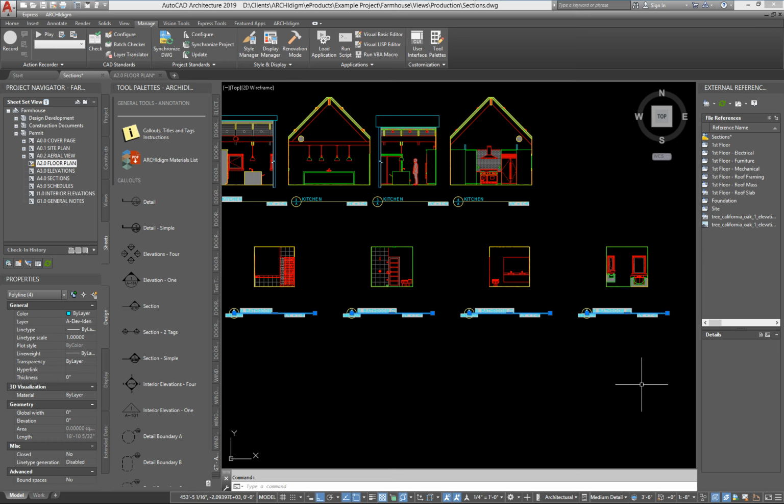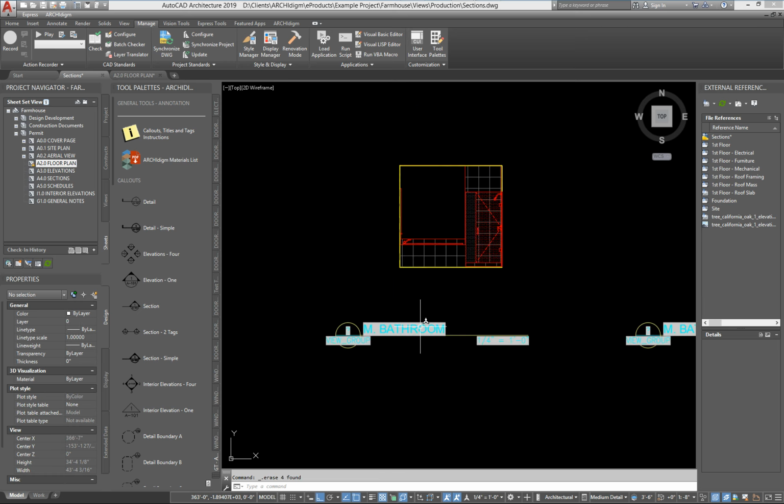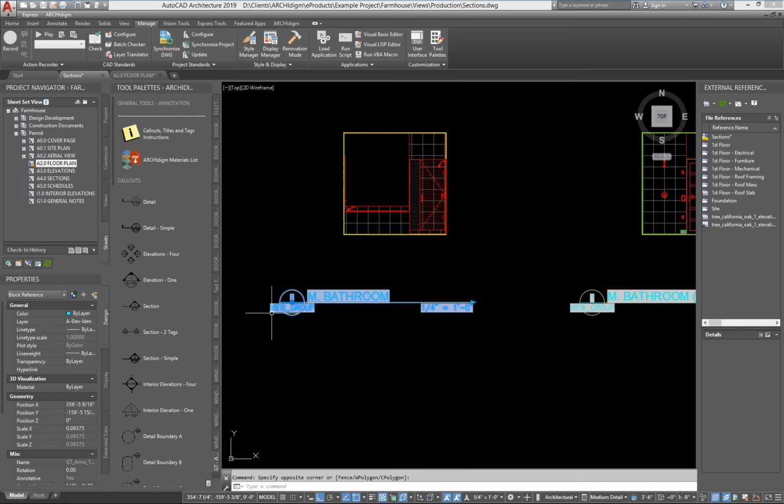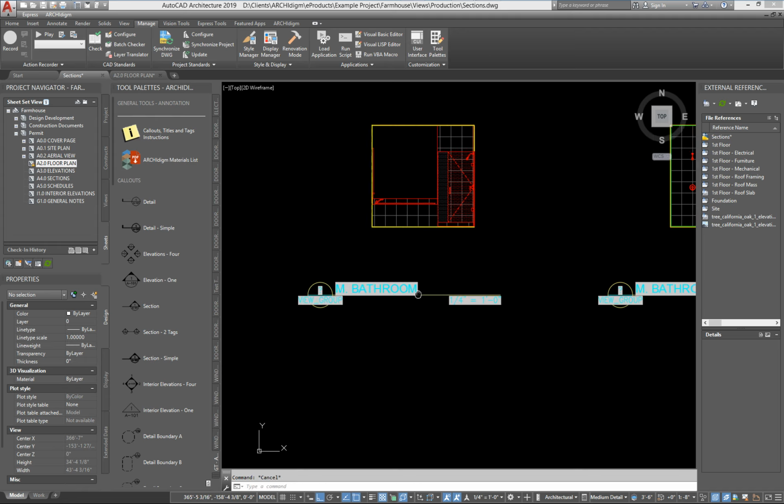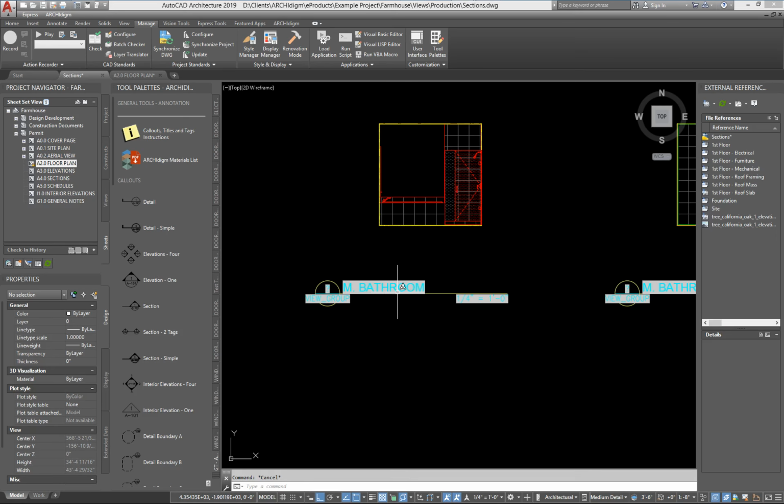It's just a click on that line, and get rid of it. Now what's left here is an update to the original titles, which were made before dynamic blocks were available. So these are dynamic block titles. And I think they're better because they're just single things with a little grip on there and some other options as well. So for example, let's say I want to take this and bring it over.